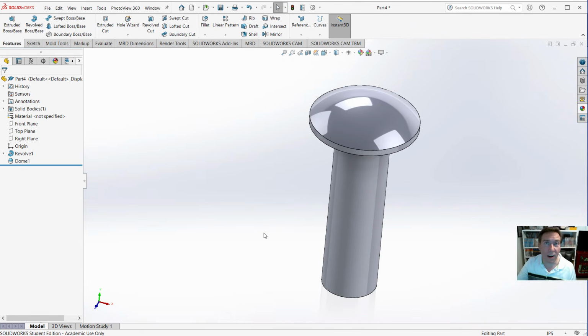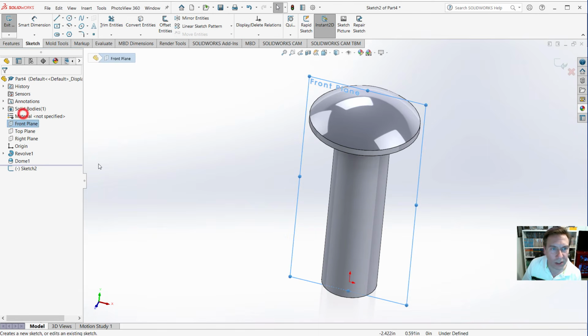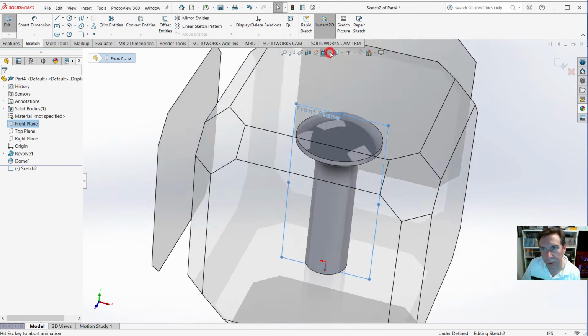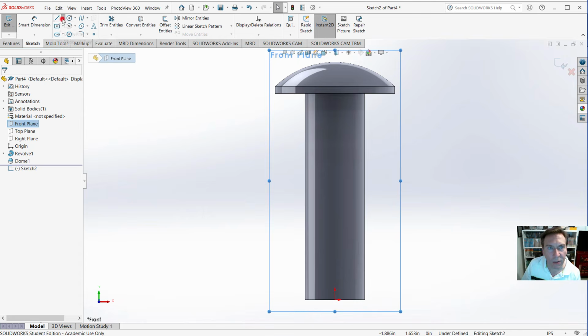Otherwise, you just draw an arc across in the sketch and make sure that the back line goes up 2 inches. Now to make that little cutout, because my keyboard's dead and I don't want to stop the video, I'm just going to go to Sketch, and we'll go over here to the front view orientation. I'm going to draw a center line.